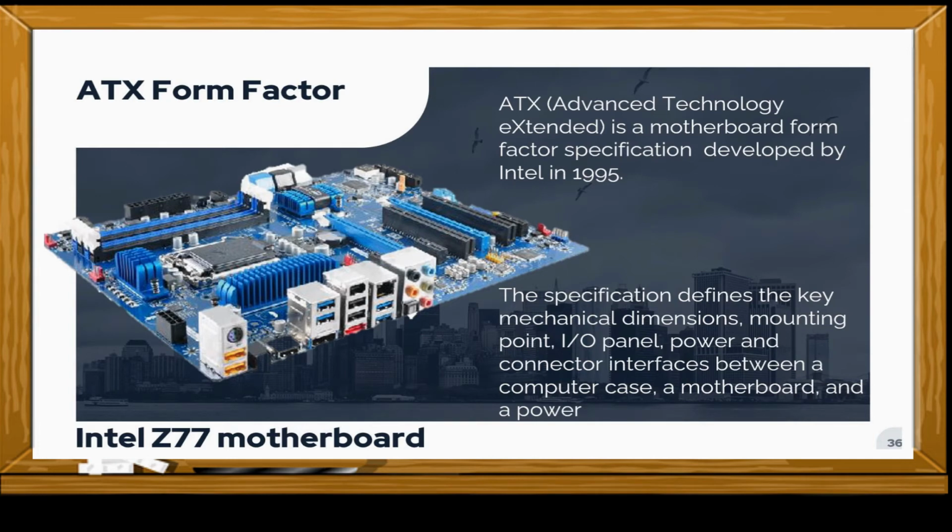ATX, or Advanced Technology Extended, is a motherboard form factor specification developed by Intel in 1995. This specification defines the key mechanical dimensions, mounting points, the input-output panel, power and connector interfaces between a computer case, a motherboard, and a power supply. The Intel Z77 motherboard is an example of ATX form factor.